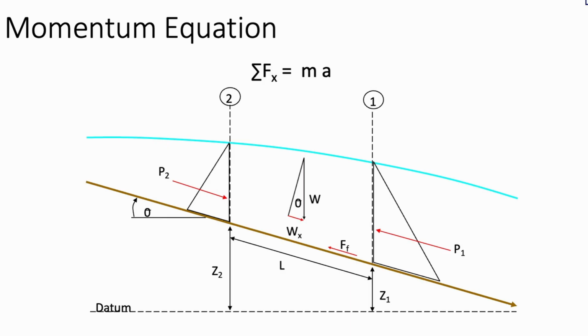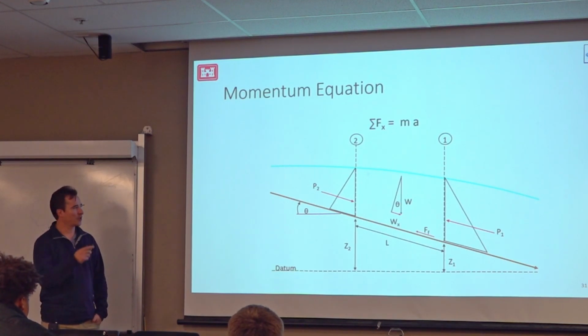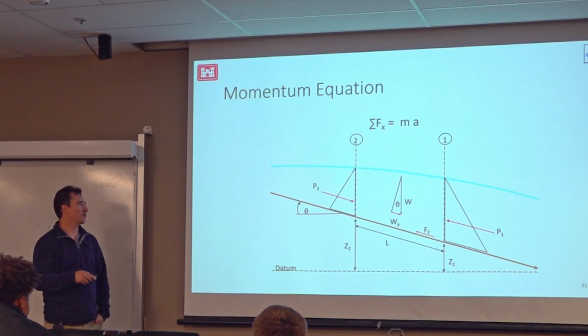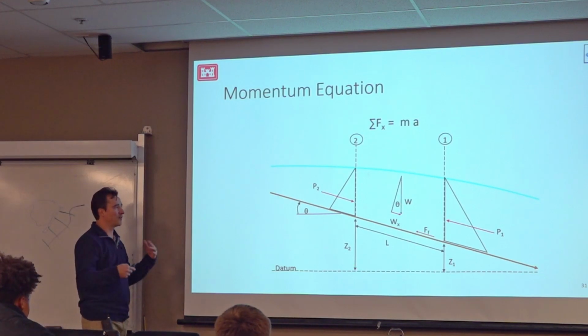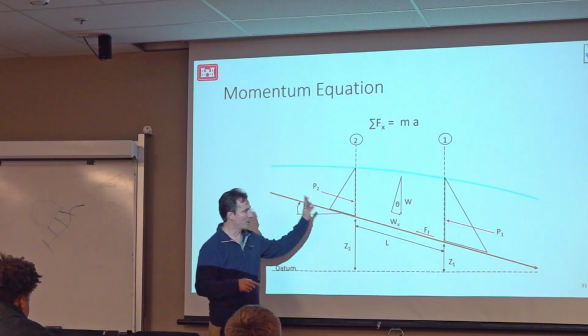All right. So in certain cases, the energy equation doesn't work very well, like at low flow bridges or places with rapidly varied flow. And so you want to use the momentum equation. So we're going to introduce that here. And what this diagram is showing is a balance of all the forces for a volume of water inside of a channel.